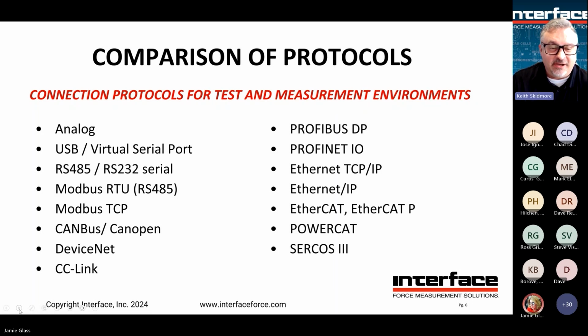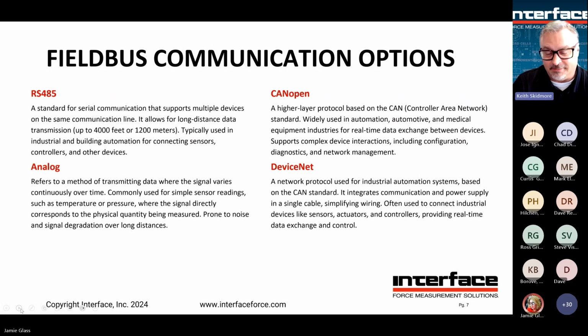One thing to be careful of is many of these protocols sound similar, so you might think they are compatible. For example, Ethernet TCP/IP and EtherNet/IP. Hey, those sound pretty much the same. Turns out they are completely incompatible in that if you buy, say, an EtherNet/IP device, it's not going to work on your Ethernet TCP/IP network or vice versa. Certainly, it could be made to work with converters and things, but they're not natively compatible with each other. Same thing with various Ethernets and EtherCATs and EtherCAT-P. They aren't the same, and they would connect differently. Same thing with Modbus, RTU versus TCP, different.